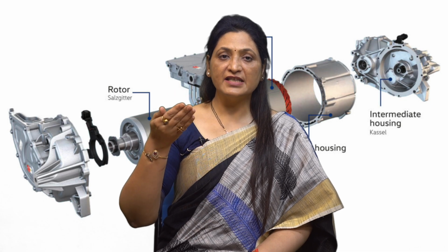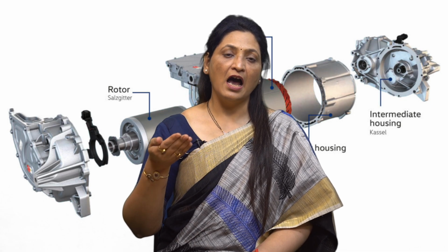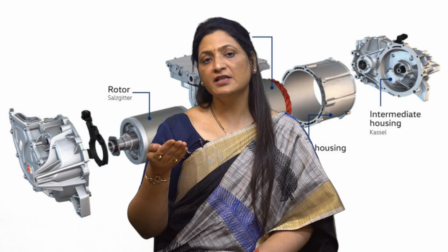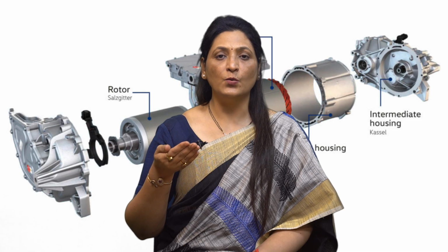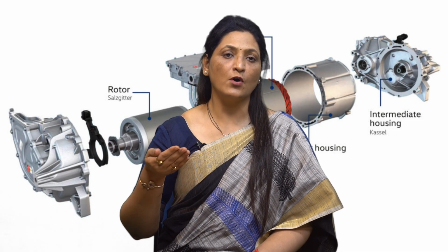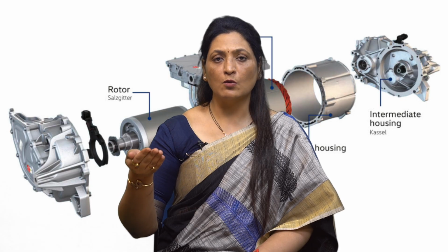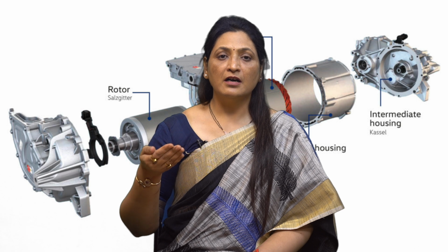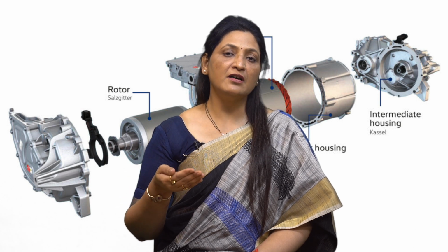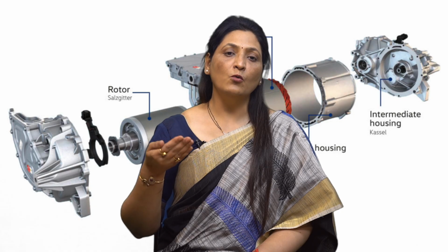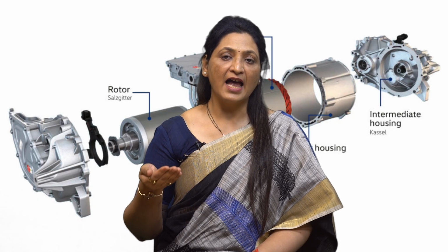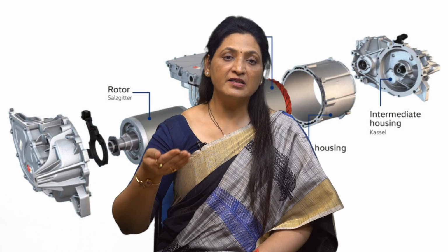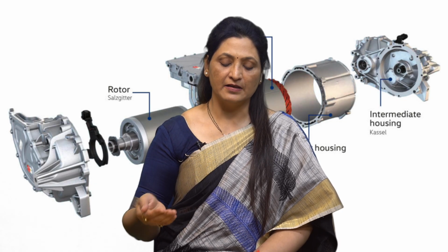The main components, as we have discussed, are motors, power processor, control unit, and electrical source. The load is usually mechanically designed to achieve a given task, for example, fans, pumps, robots, washing machines, machine tools, trains, drills, etc. The load requirement can be specified in terms of speed and torque demand. A motor having speed-torque characteristics and capabilities compatible with the load requirements is chosen. So, let us discuss the components one by one in detail.